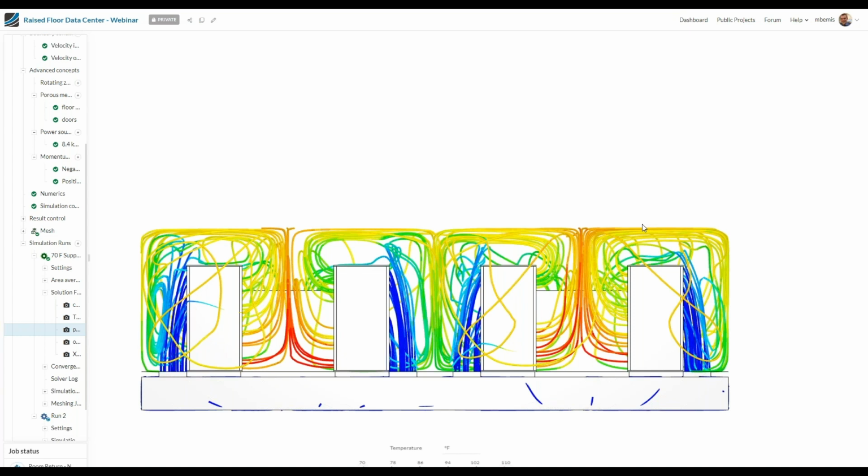Sometimes data center operators try to combat this by setting your supply airflow cooler, driving down the thermostat. It's really just an expensive patch. You don't need cold air. You need less of your hot air going into your data center servers, into the inlets.